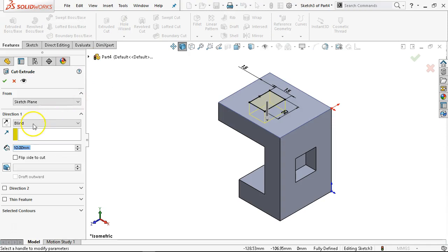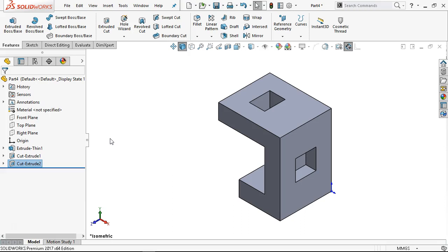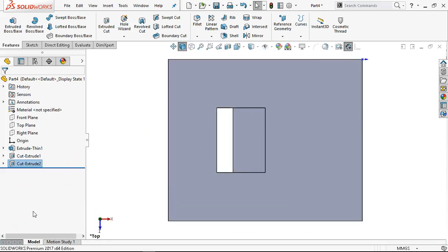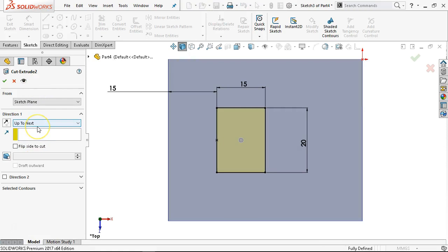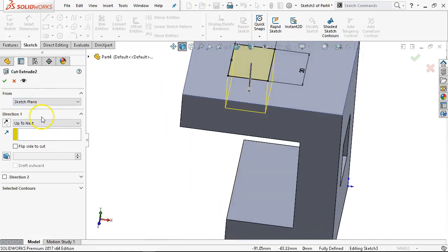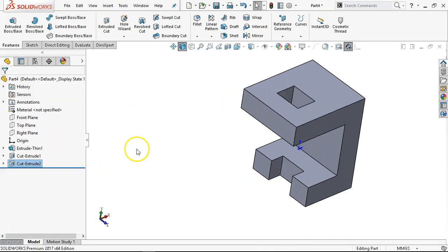All right, so extrude cut, and up to next. And there again we have those fun square corners. So whenever you see square corners, that should be a red flag. Are we 3D printing this? If we're not 3D printing it, then my round tools do not make square corners. So are we wire EDMing it? Looking at it on the sides, we have an intersection. If I had done the through all, I probably did that on autopilot. I went up to next instead of through all, because through all will do exactly what it says it's going to do. Blast it through the lower leg.